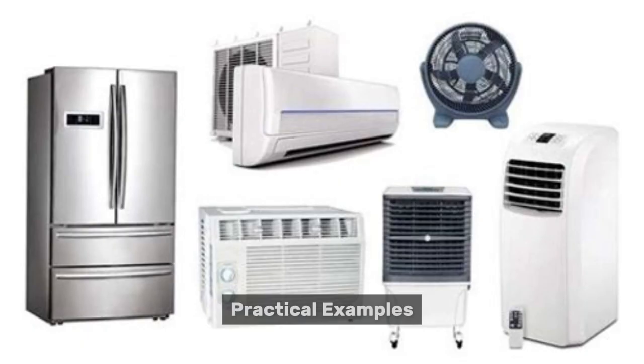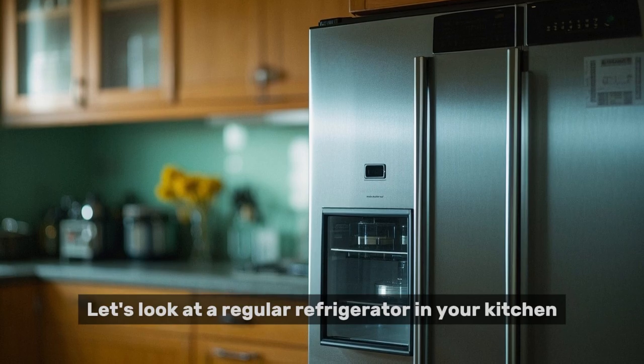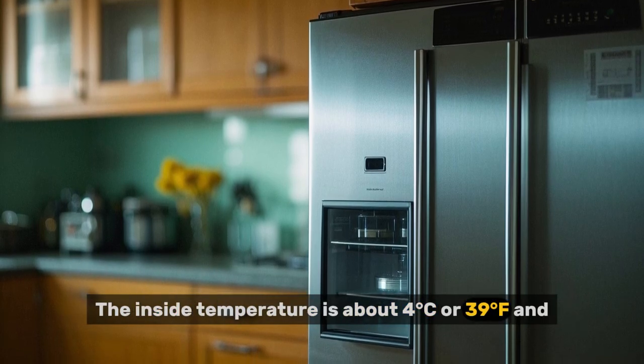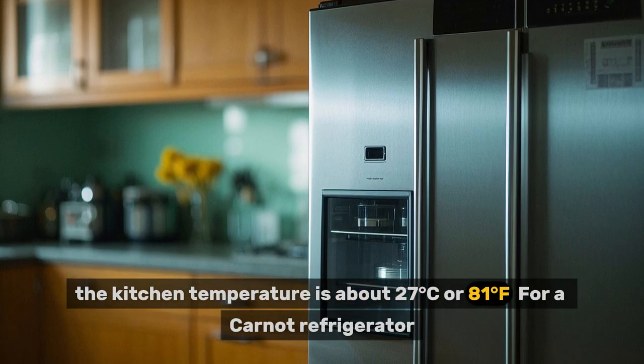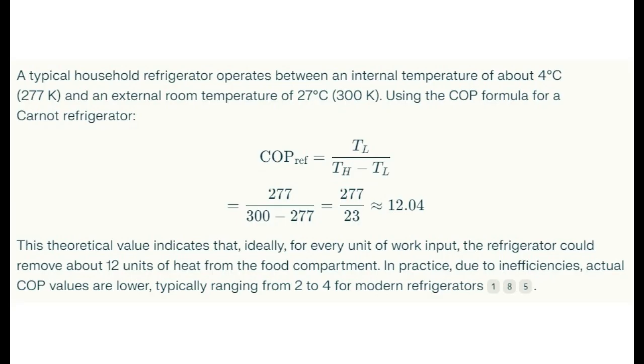Practical examples. Let's look at a regular refrigerator in your kitchen. The inside temperature is about 4 degrees Celsius or 39 degrees Fahrenheit, and the kitchen temperature is about 27 degrees Celsius or 81 degrees Fahrenheit. For a Carnot refrigerator, best possible COP equals T-low divided by T-high minus T-low.